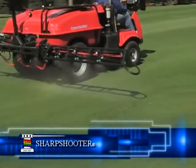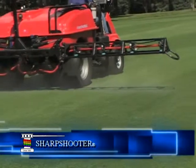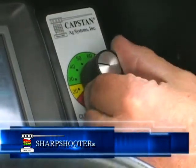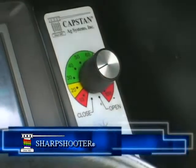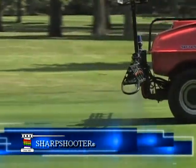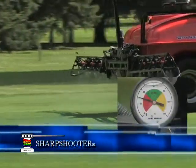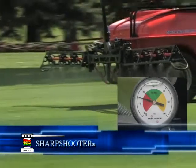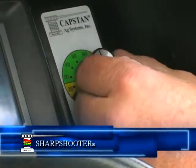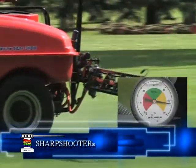Sharpshooter utilizes drift reduction tips, but also affords the operator further on-the-go drift control. The operator simply dials the Sharpshooter control to a lower pressure. The operator selected lower pressure provides bigger droplets and fewer driftable fines. The application rate and speed are maintained independent of this pressure change. Once the drift concern is passed, the operator can dial the pressure back to the original pressure set point for optimum efficiency.